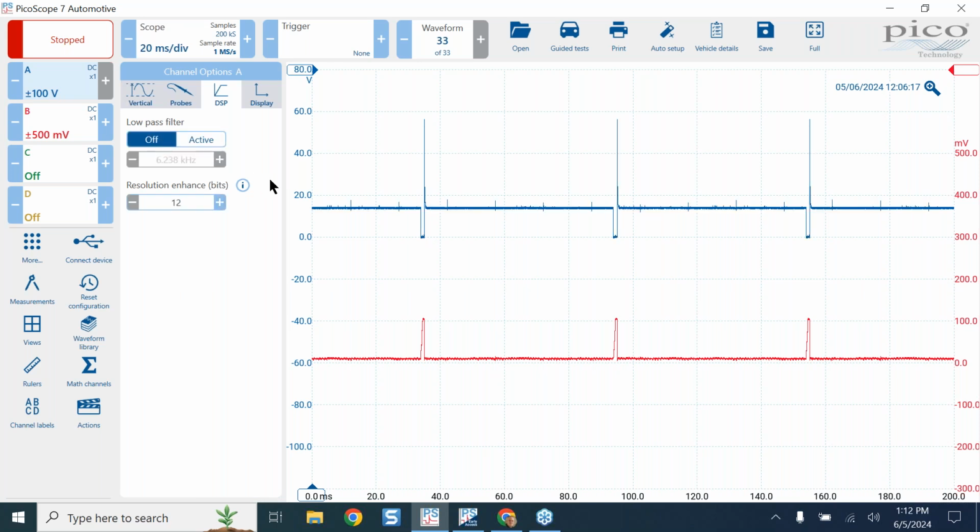Now, just a couple notes about filtering. Filtering is not for the scope. The scope doesn't care about filtering. It doesn't care how you filter it. The trigger is still going to trigger off of the raw data or the unfiltered signal. So filtering is strictly just for us, the user. It's for our eyes. Maybe we're trying to analyze and we're trying to pick out what's important and what's not. Sometimes we're in a very noisy environment, or the leads are run across something that's very noisy and we have to remove that. Again, it's not really necessarily for the scope.